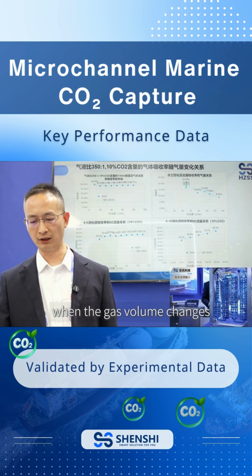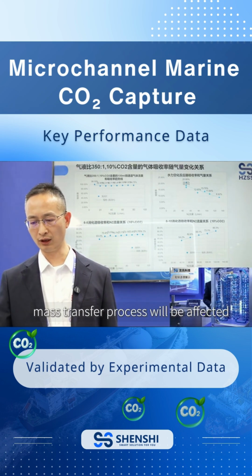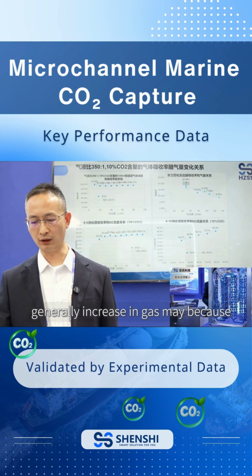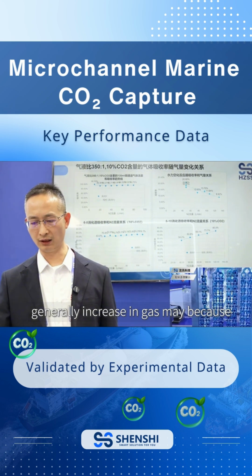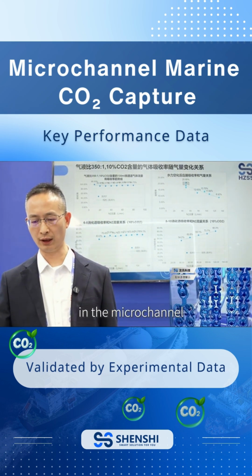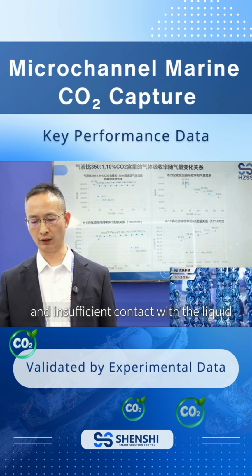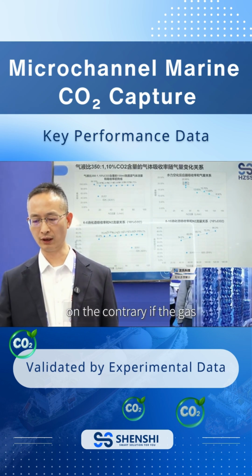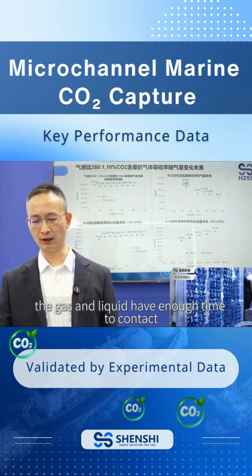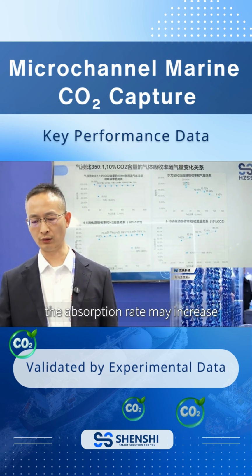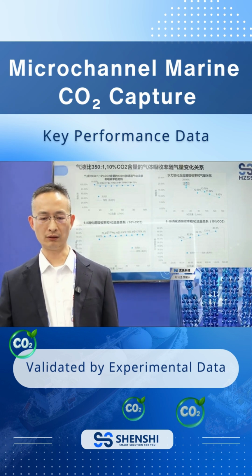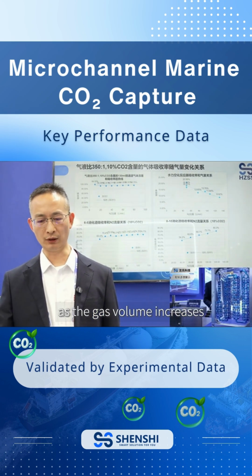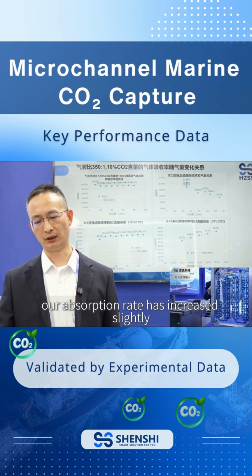When the gas volume changes, the contact between gas and liquid and the mass transfer process will be affected, which will affect the absorption rate. Generally, an increase in gas may, because of the residence time of gas in the microchannel, cause insufficient contact with the liquid, which will affect the absorption rate. On the contrary, if the gas and liquid have enough time to contact, the absorption rate may increase. But from our current data, as the gas volume increases, our absorption rate has increased slightly.